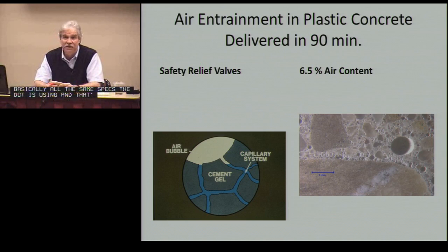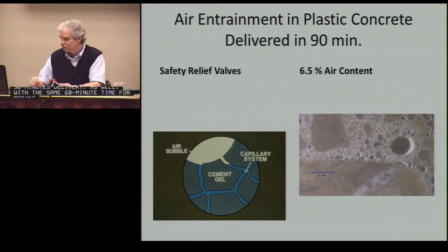There's also Type 1 concrete by the DOT that has no air. That's a 90-minute delivery as well with the same 60-minute time for adding water to the truck. So all those things follow the same DOT system as the intent.